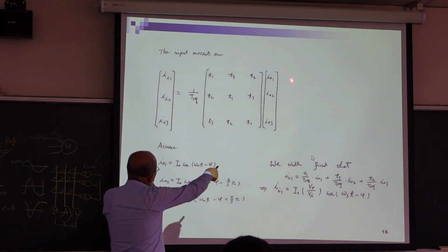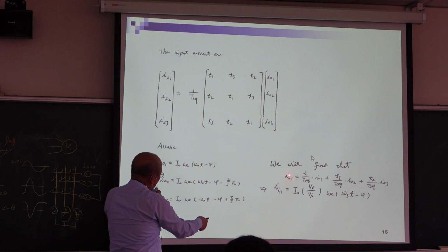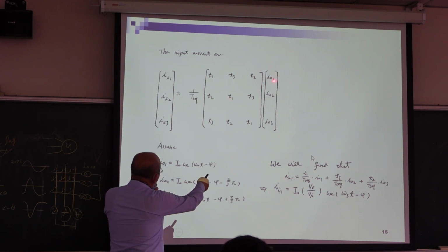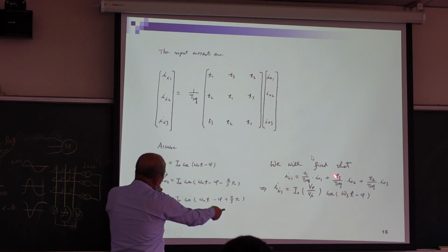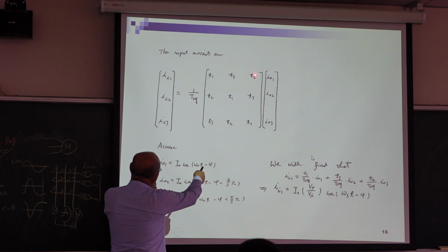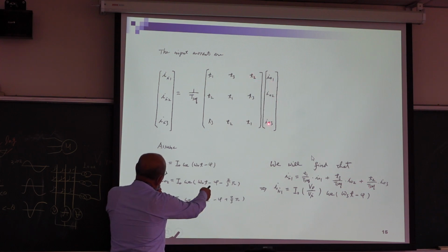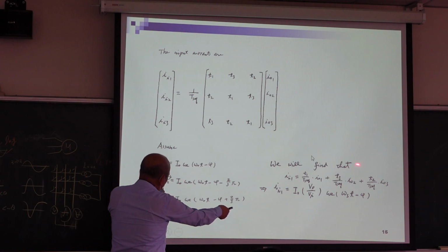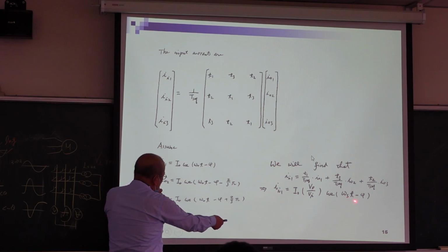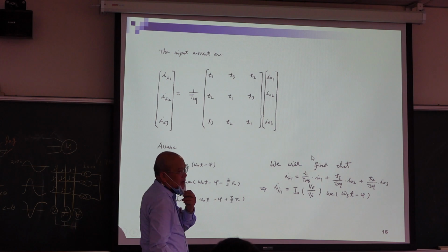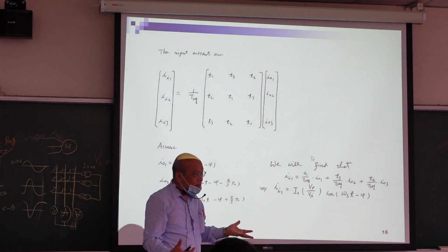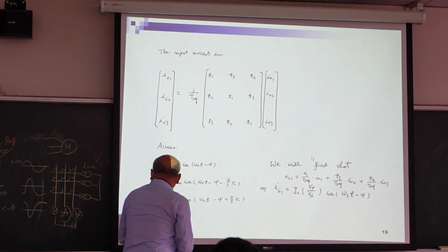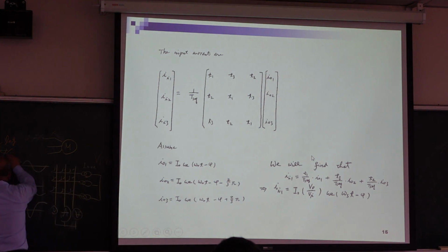So you can compute this equation. II1 is T1 sequence multiplied by IO1, plus T3 sequence multiplied by IO2, plus T2 sequence multiplied by IO3. So finally you find whether the input current is leading or lagging. Also lagging, right? Output is lagging 37 degrees. How about the input?